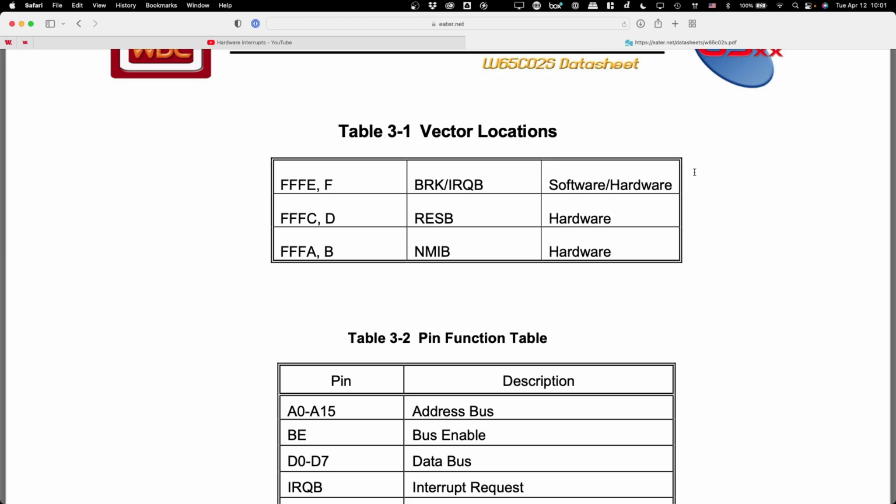So now, why would you want to do that, though? Essentially, what you'd be doing is what I said before, which is periodically checking to see if I need to do something. That would be equivalent to just polling the hardware that might cause the interrupt to see what its values are. So for example, I could poll my buttons and see, has the button status changed in any way?